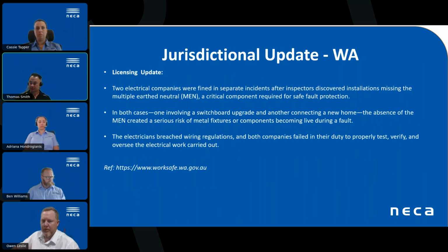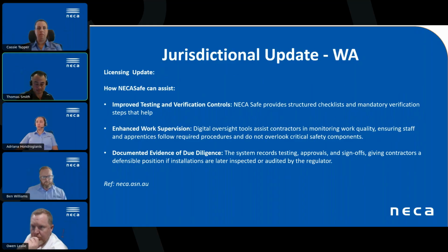Next slide, Owen. Bit of a licensing update here. So 2 electrical companies were fined in separate incidents after the inspectors discovered installations missing the MEN, obviously a critical component within the system. In both cases, one involving a switchboard upgrade and another one connecting into a new home. And obviously the absence of the MEN created serious risks of the metal fixtures or components being live during a fault. The electricians breached wiring regulations and both companies failed in their duty to properly test, verify and oversee the electrical work carried out. I'll hand over back to Ben.